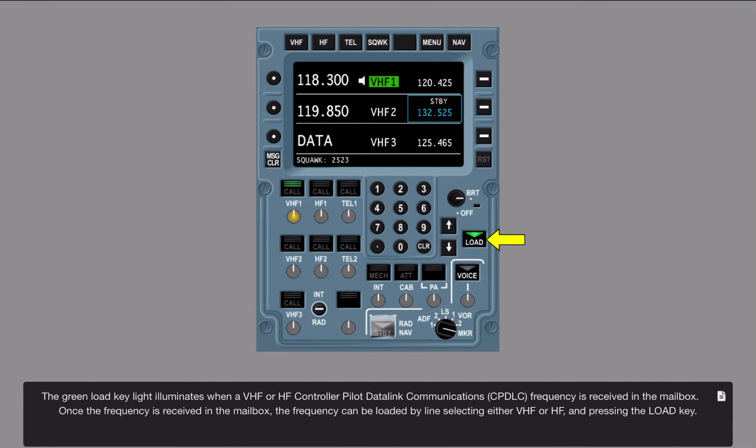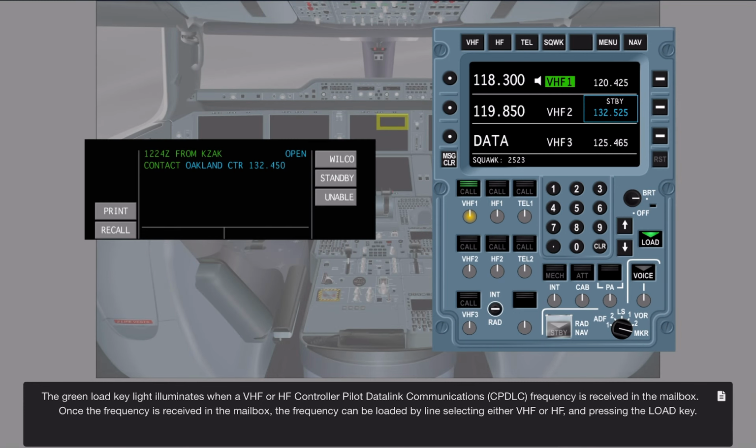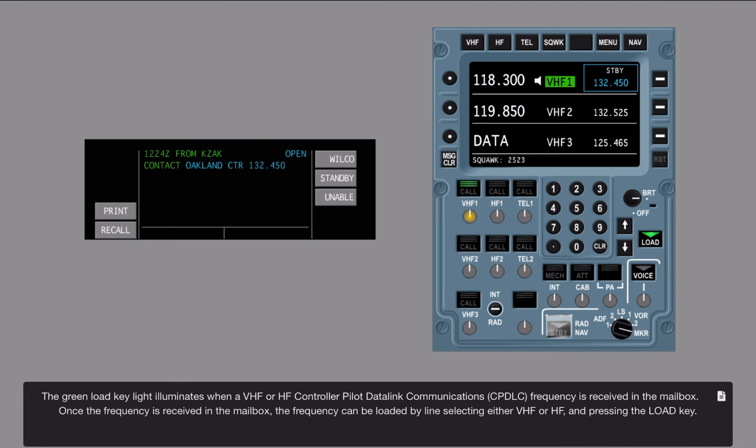The green load key light illuminates when a VHF or HF controller pilot data link communications, CPDLC, frequency is received in the mailbox. Once the frequency is received in the mailbox, the frequency can be loaded by line selecting either VHF or HF and pressing the load key.